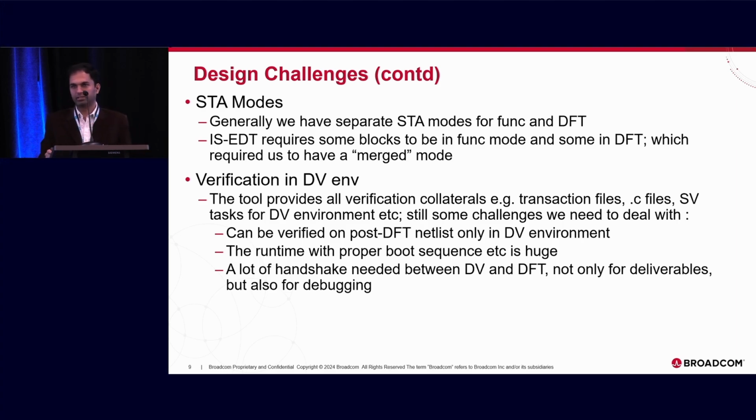Another problem which we faced was this STA, right? Now, generally, the way we do the STA, it's different modes for DFT and different modes for functional. Now, this is kind of a tricky mode where we have some blocks in functional, some blocks in scan. So we came up with a merged mode, but we also had to come up with some innovative ways to actually cover most of the paths in the existing modes, and then we came up with a merged mode as well. It would need a completely separate presentation if we were to cover all the things which we did for STA, but I just wanted to mention here that it adds some complexity to STA as well.